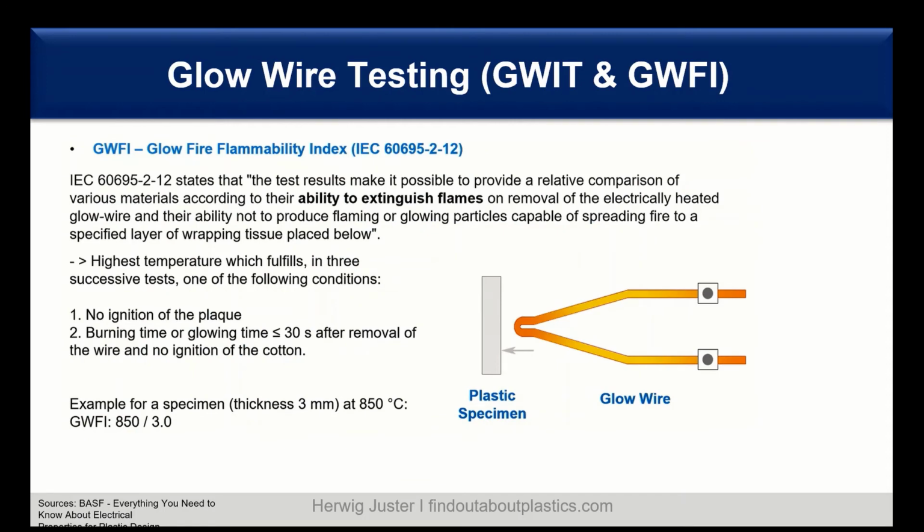Then we continue with the glow wire testing. So there's the GWFI according to IEC 60695, and you can see here we have again our specimen, our plastic specimen, and a wire which is heated up and then touched on the specimen.